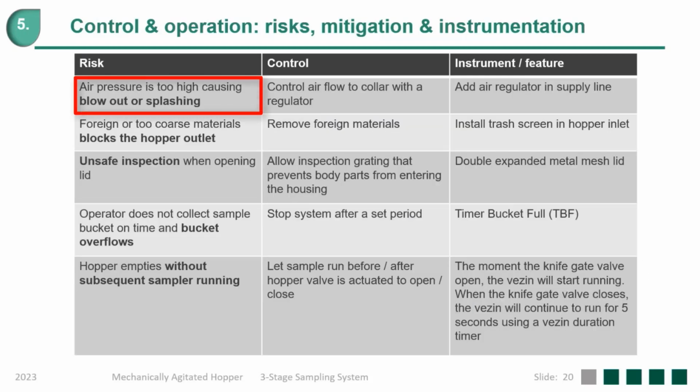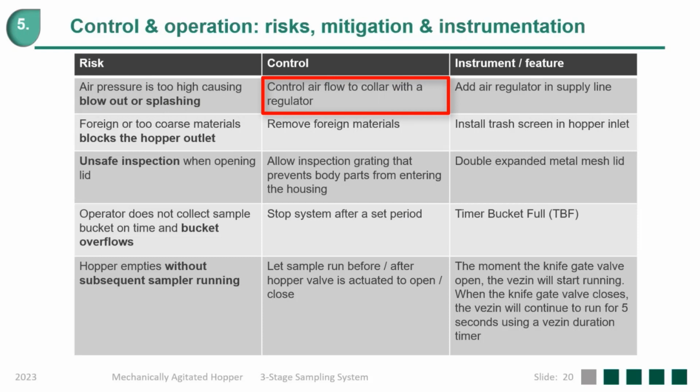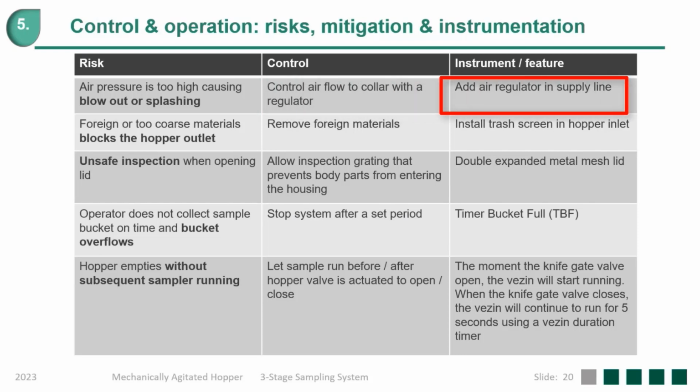Air pressure is too high, causing blowout or splashing. We control that by limiting airflow to the collar with a regulator. And then we need to add a regulator in the supply line.